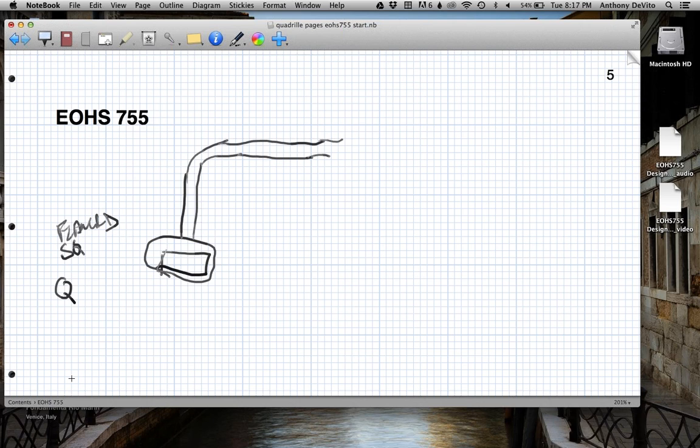So now, before we worry about transport velocity, we want to know what distance the worker is going to be working from this flanged hood. Pick a distance. Let's make it a foot. 6 inches, 60. I have to be right up against it. Let's make it a foot. Okay, so the distance is 1 foot. That's our x, right? So if I look at the formula here, I'm going to use the bottom formula. I know what x is.